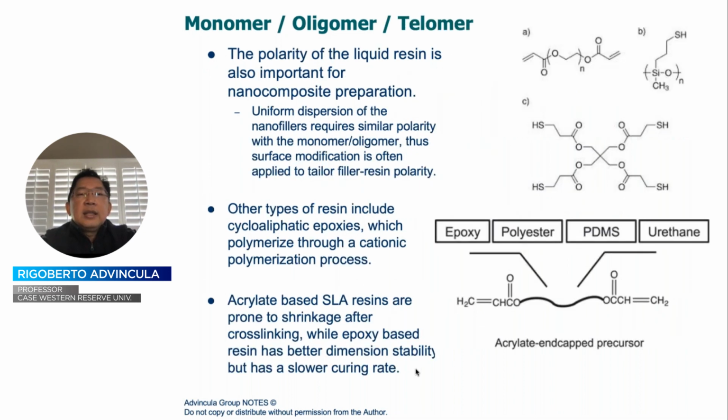So let me skip this and instead focus on some of what we call telechelics. So a polymer species or macromonomer species, or even a filler material which contains, let's say, these acrylate groups or even the thiol group, which can have a cascade effect on the photopolymerization method, can be actually part of any material, whether it's a polymer or polymer backbone, or even the nanofiller or filler itself. Essentially, when we say the word telomer or telechelic polymer, these are ingredients that are already existing polymers or macromolecules, yet they have a reactivity because of the presence of the acrylate group. So let's just lump that species as macro cross-linkers or telomeric or telechelic species.